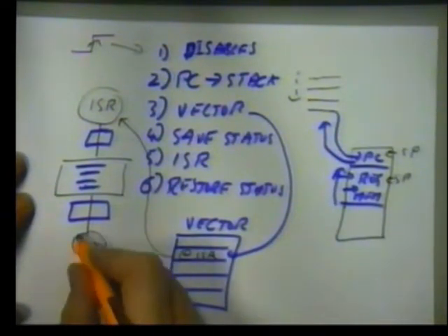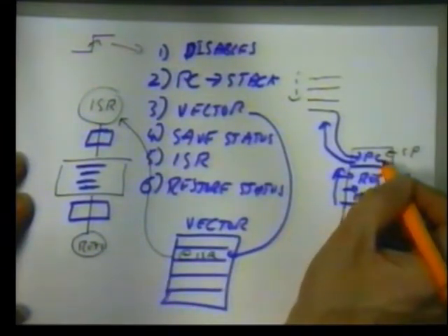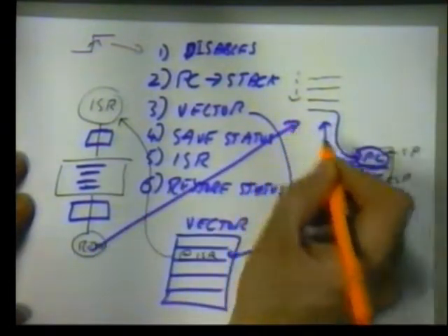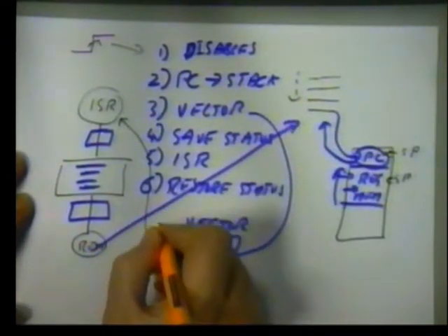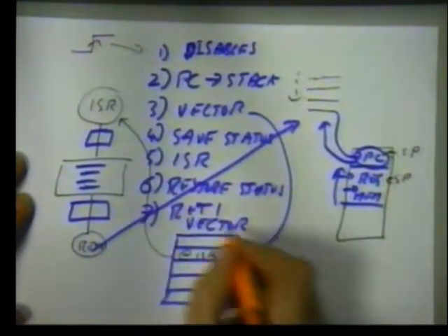It's usually a special instruction, return from interrupt. That means you go to the stack, you find the program counter, you return to where you were, and finally, automatically, we return with RETI and we re-enable our interrupts. That is the complete process of an interrupt service routine. So there's a penalty. You've got these wonderful parallel processes, but there's a lot you need to do.